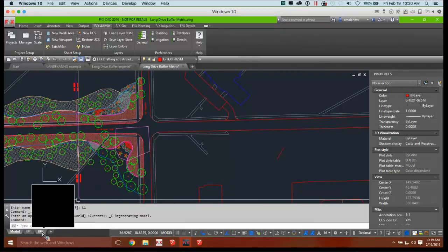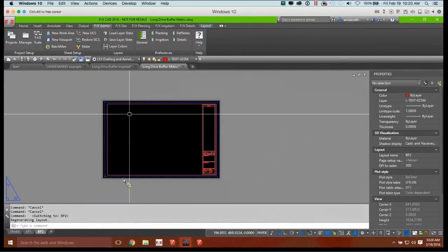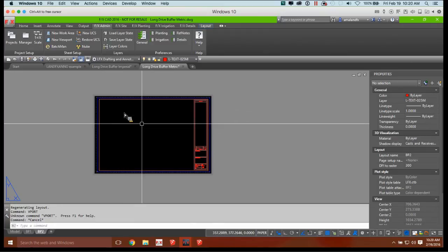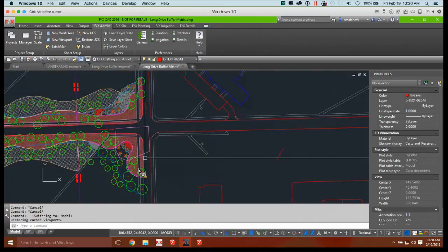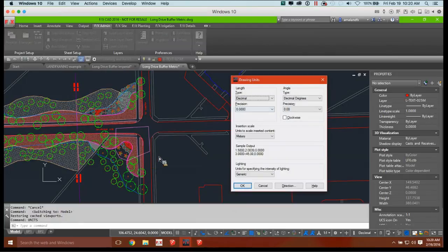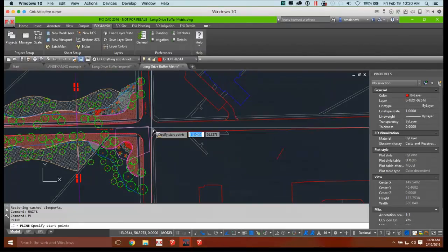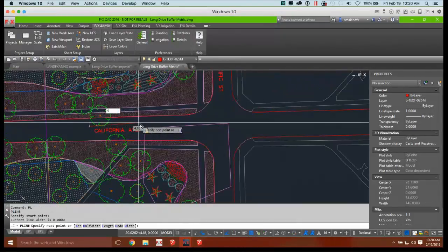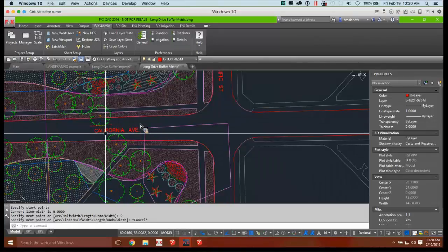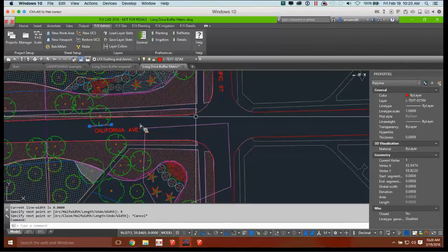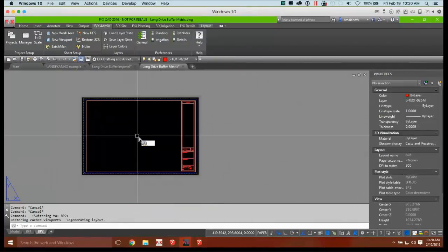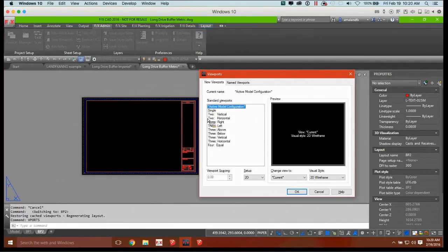As I go over to my sheet, you'll see I don't have a viewport yet, so I need to set that up. I'm going to go ahead and pull in a viewport. Oh, and before I do all of that, I'm going to go back and check my units. Yep, decimal meters, okay, and I'm going to draw a line and just check, and we're going to type just 9, and yeah, that's meters. Definitely not millimeters or centimeters or inches or feet. Okay, so back on track. I'm going to grab my viewport.